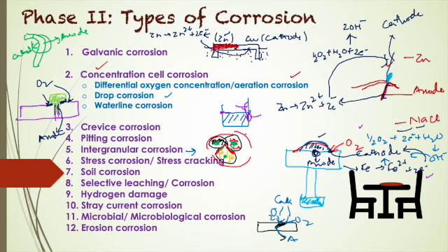So during that process, it is supposed that these bacteria convert the oxygen from the sulfates into such a form which brings about a depolarization effect on the corrosion of iron. When these organisms die, sulfur is liberated as H2S, which converts a portion of the corrosion product into FeS. Iron metal is converted to FeS, which is less effective. So corrosion can speed up or take place in that way.